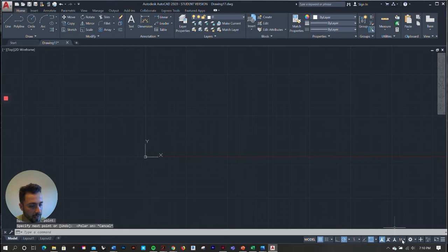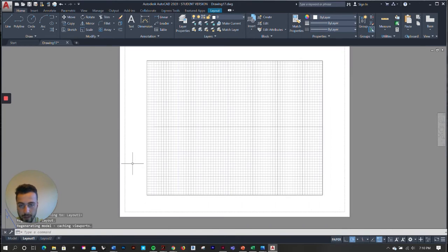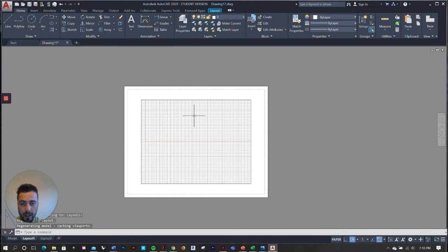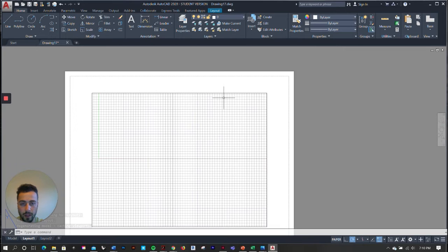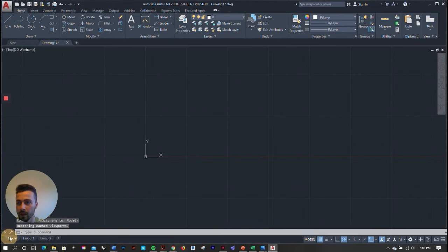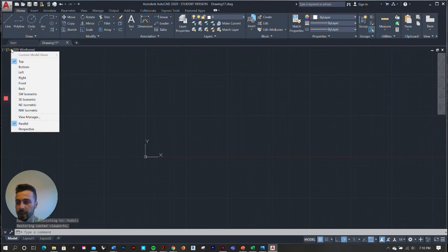As you can see here, the drawing scale is 1:1. I usually draw at a scale of 1:1. And then when I want to publish or print it, you can always change that in the layout tabs, which is where you'll see your piece of paper as well as your viewport.